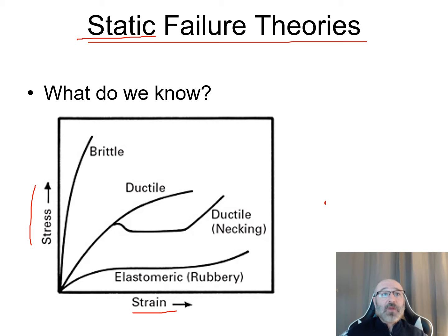If we're talking about brittle material, we can see a very, very steep curve coming up for that type of brittle material. What we know from that is it's going to be a very little bit of strain for quite a lot of stress. We're going to see a lot of stress on this object and not much strain. And it's going to be a real brittle, quick failure once we get up to that loading. It's not going to change. It's not going to actually deform or strain very much.